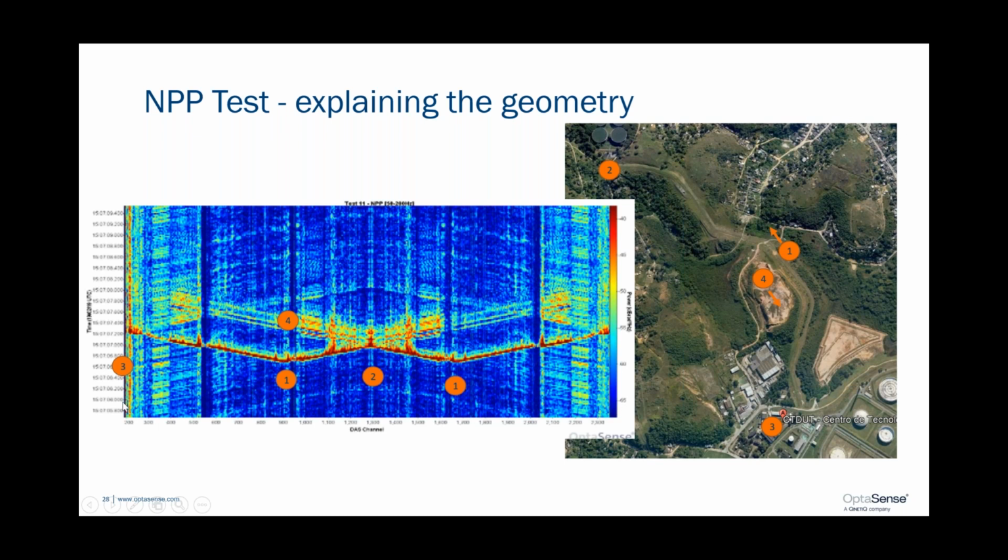So this is the live waterfall trace from one of our negative pressure pulse burst events. We're looking on the x-axis at distance away from our operating base, and the fiber goes up to the end, and then it loops and comes back inside the same cable, just using a different core. And then this is time, and then we have intensity just color coded. So we can see where the failure happens. Well, it happens twice, which is confusing.